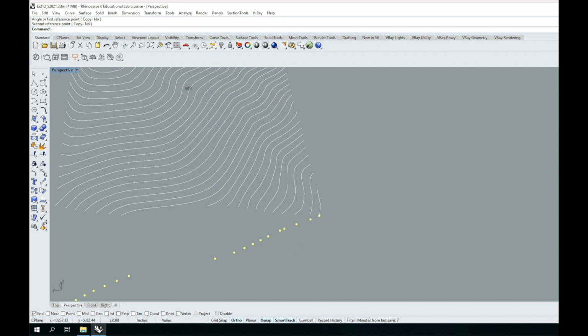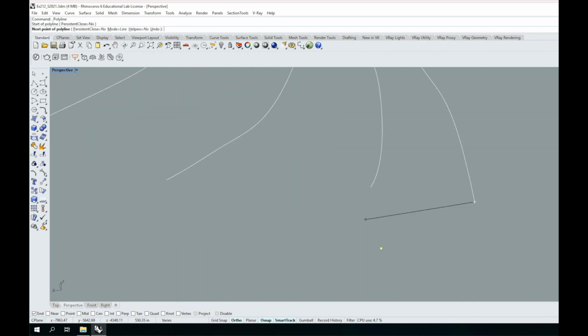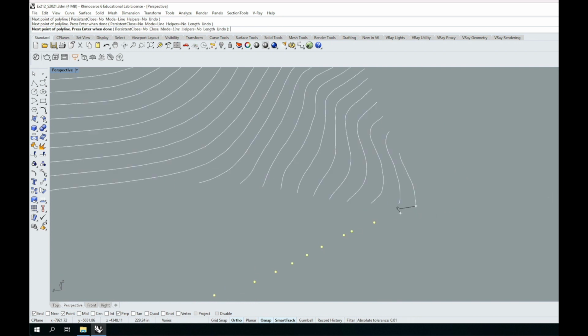And then I'll go ahead and use those points to draw the steps. So I'll come over here to the polyline tool. I'll start at that first point. And as I draw, I'll come over here and I'll snap. Let me make sure I have points on so that I can snap to points. And we'll come over here until I meet up at perpendicular. Let me turn on perpendicular snap. There we go. So I'll set that, come over here, and there's perpendicular. And we'll continue drawing with each one of these steps. So again, I always want to snap to perpendicular at each step.